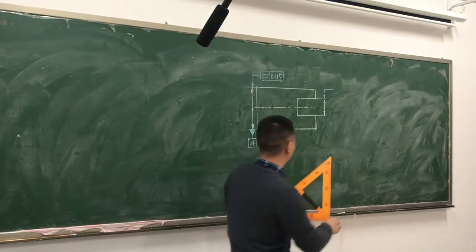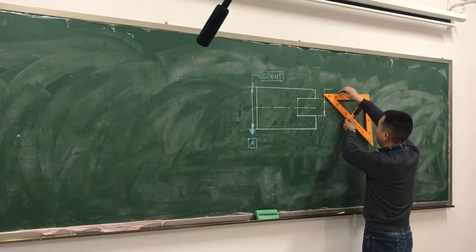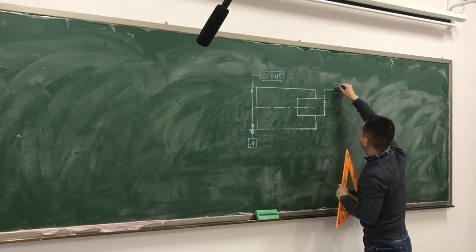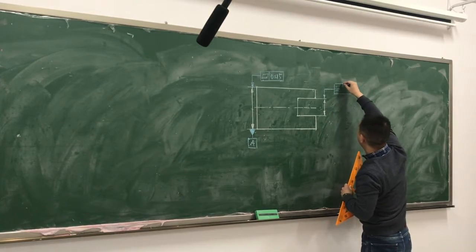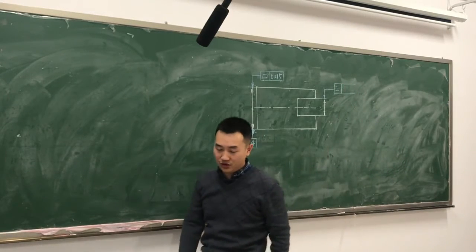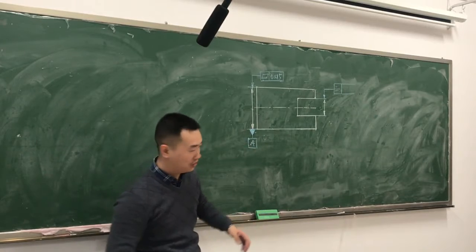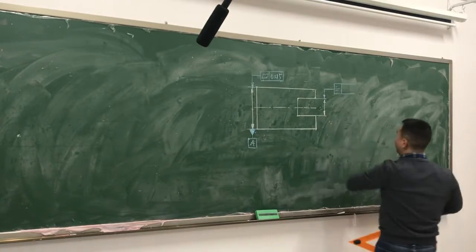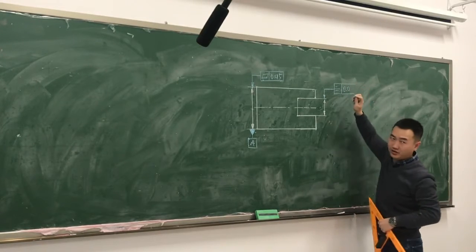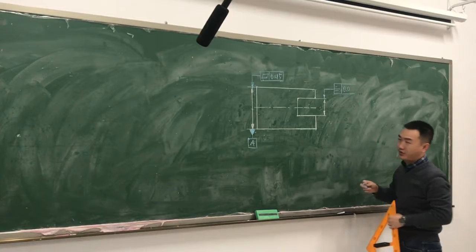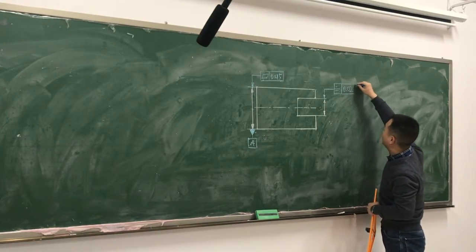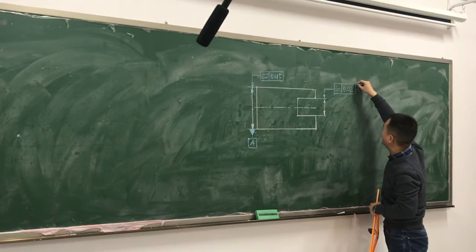And here, you just add the symmetry symbol here. And here, the tolerance value, should I put 0.01 here or otherwise? In fact, we should multiply the given value by 2. And the tolerance datum is A.